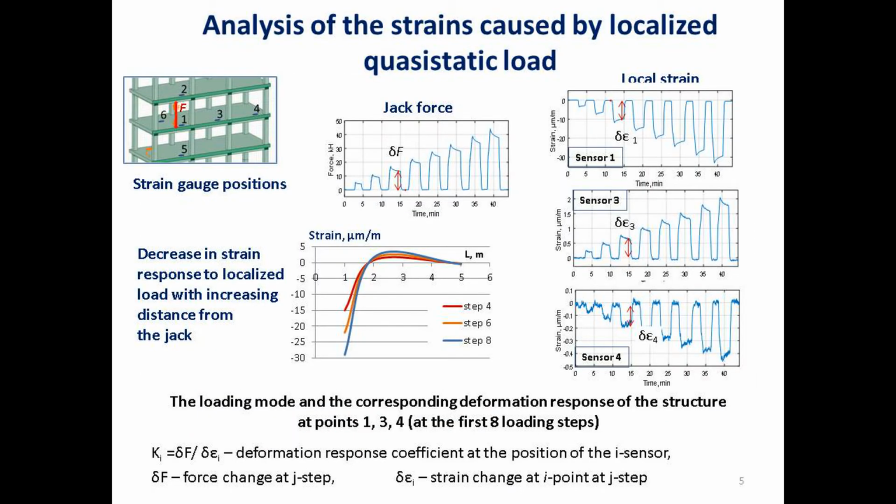This slide demonstrates the deformation response of the structure to a localized static load during 8 initial loading steps. We can see that the strain value decreases rapidly when the distance from the loading point increases. We propose to characterize the deformation response to the applied static load using the coefficient K. For a specific point of the structure, it is equal to the ratio of applied force at a certain loading step to corresponding local strain. This coefficient changes at each loading step, and we can trace how this value varies with increasing load.